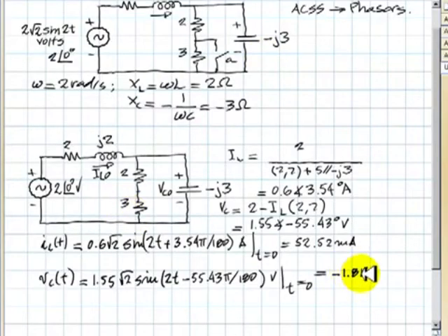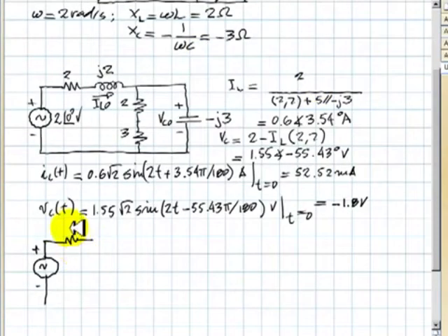What this means is that the initial voltage in the capacitor actually was not like this, but like that, 1.8 volts. So if I want to write it here, it's the same. Good. We are ready to go to the Laplace domain solution with this switch closed, which eliminates, bypassing, this resistor. Now we're going to represent the inductor with an initial condition source in series with an impedance, SL. Right. The initial condition is going to be L times IL naught, in this polarity.